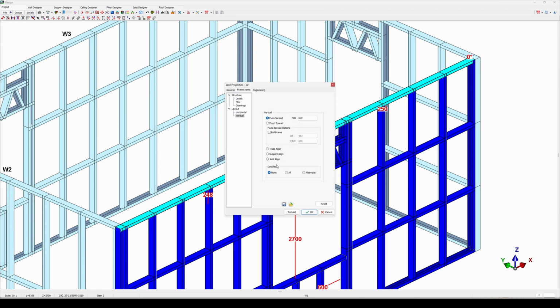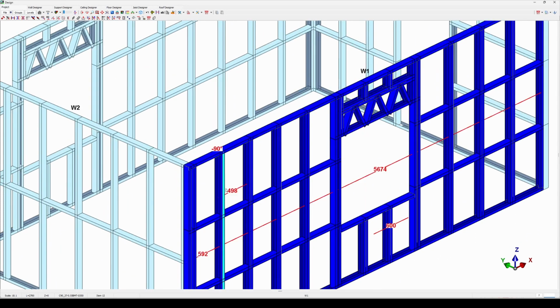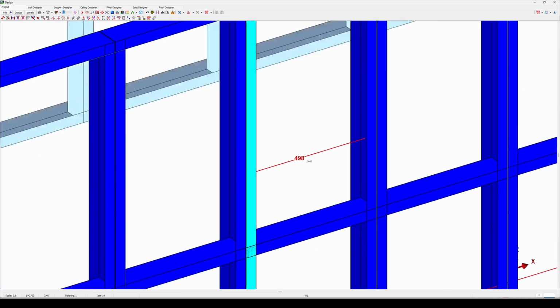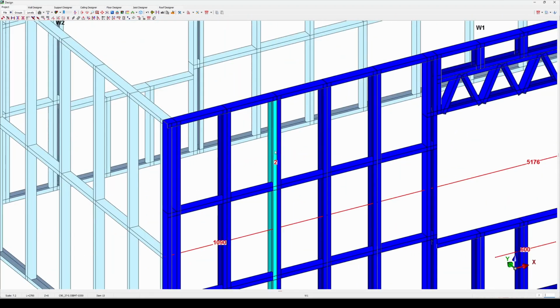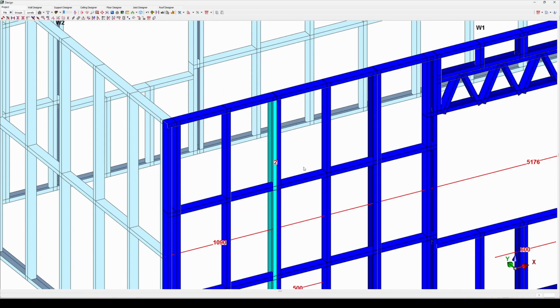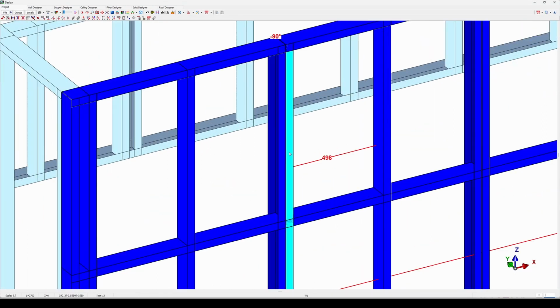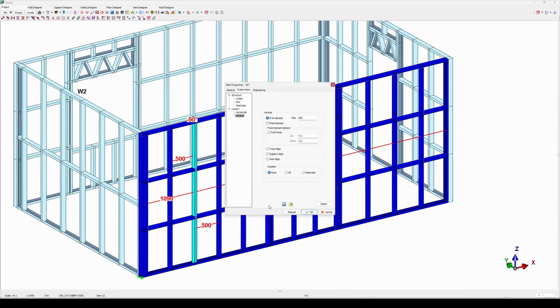Same for your joists. As soon as we go to the doubles option, what that does is it changes all of your studs or every second stud to be a back-to-back member or a double. So if I change that to all, you can see all of my studs are back-to-back. Or I can change the setting to be alternate and hit rebuild. So every second stud is doubled up. So make sure to keep it on none unless you are informed otherwise by your engineer.